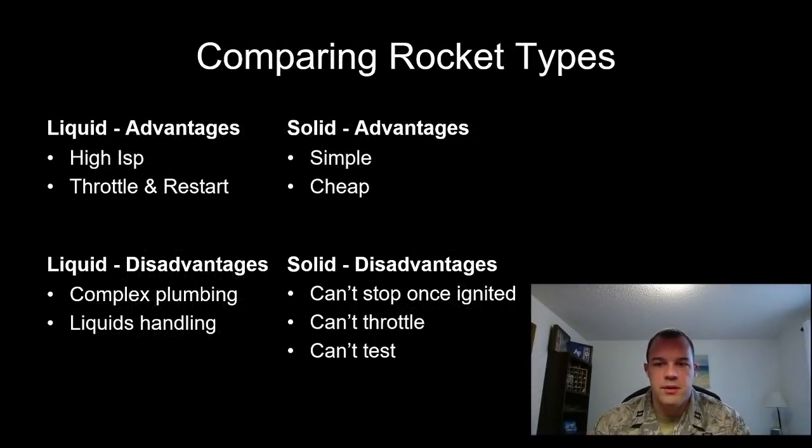Now, this is an important thing to understand here. We're comparing the advantages and disadvantages of a liquid and a solid rocket. Those are usually the best to compare in the sense that they're your first stage launch vehicles. So let's talk about engineering trades you might consider when choosing either a liquid or a solid propellant thermodynamic rocket. Now, the advantages for a liquid rocket are that it has high specific impulse, and we'll get to that in a second. Specific impulse is essentially your gas mileage in a rocket. So you get more bang for your buck in a liquid rocket.